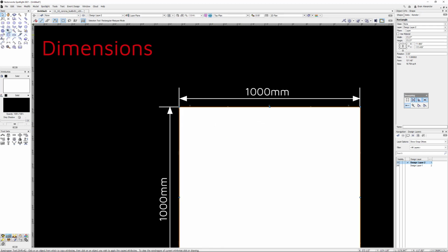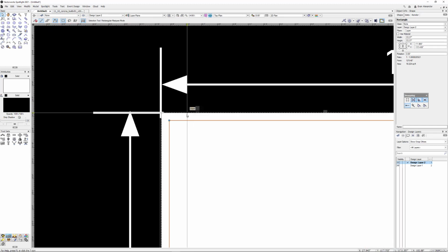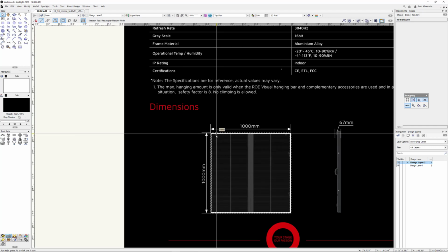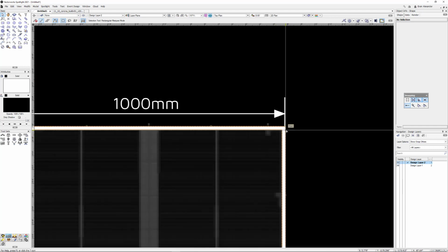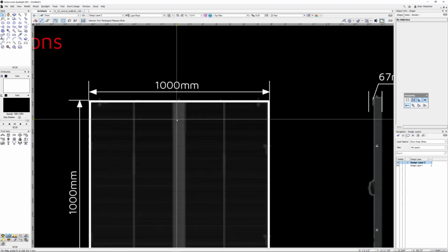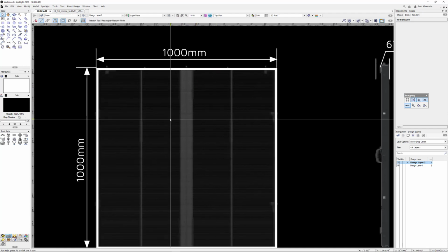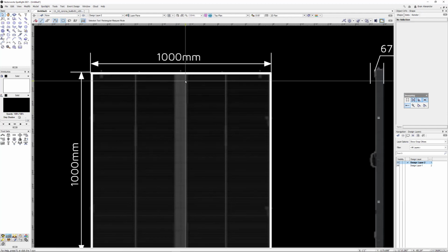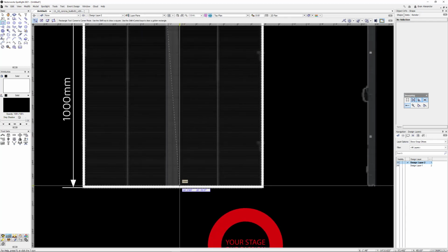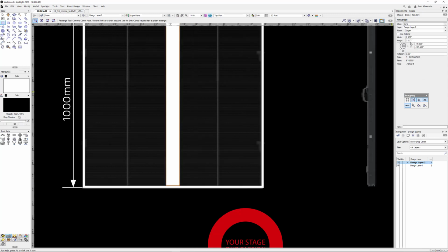So now I'm going to grab my offset tool here. And we're going to offset by a distance of 1/2 inch. And we'll come in here and we'll just click. And then I'm going to grab both of these now and say clip surface and get rid of the middle. And there we go. So now we have our outer frame here. And let's see, what do we want to do now? So let's draw it out in 2D, and then we'll start popping things up into 3D. So let's draw this center piece here and get this snapped in here.